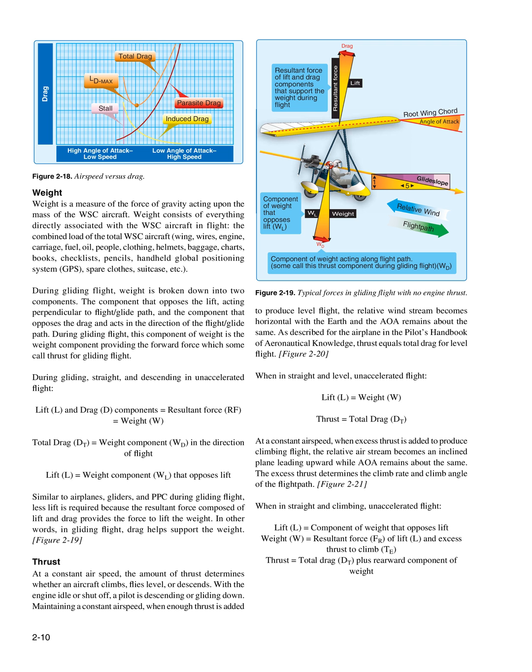During gliding flight, less lift is required because the resultant force composed of lift and drag provides the force to lift the weight. In other words, in gliding flight, drag helps support the weight. Figure 219, thrust at a constant airspeed.